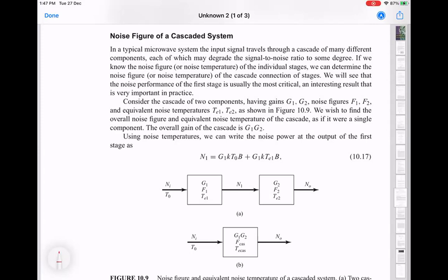The other way to think about it is that once you have some amplifier here, it tells you how good of an amplifier you need here in order to maintain the noise as much as possible, right? Basically, it means that the noise temperature of this guy needs to be small compared to gain times the noise temperature of the first guy, because that's the noise which is anyway coming in. So if the amplified noise of the first stage is small compared to the input noise of the second stage, then you will not